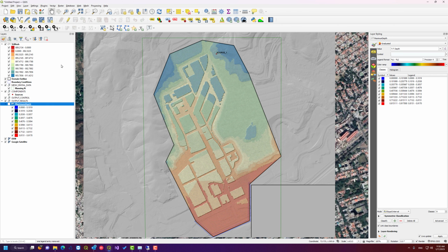So now that we run the heat transfer model, we can have different outputs that are useful for knowing, for instance, the temperature of the oil along the spill, the viscosity of the oil, the density. We can access these by going to the Results versus Time button and clicking on Oil Properties versus Time Maps.